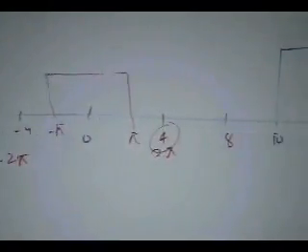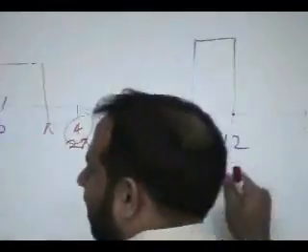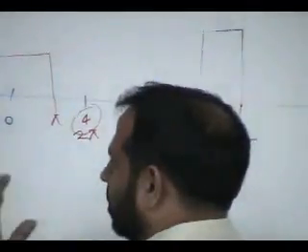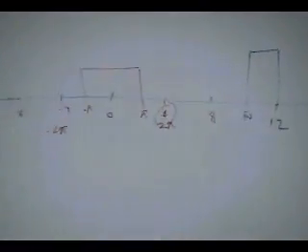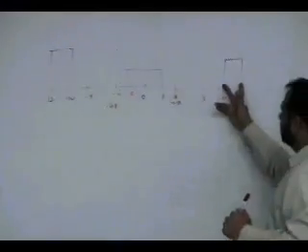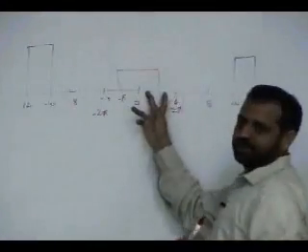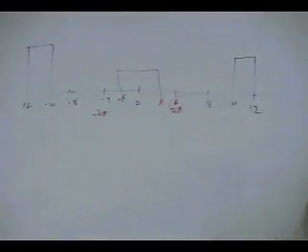Now the interesting point is, how should I figure out the minimum sampling frequency which will give me this somewhere here without any aliasing? Okay, so we'll see what that is. You need to figure that out, because you want to bring it down. The spectrum is clean, there is no point in sampling it at 24. So you do that.